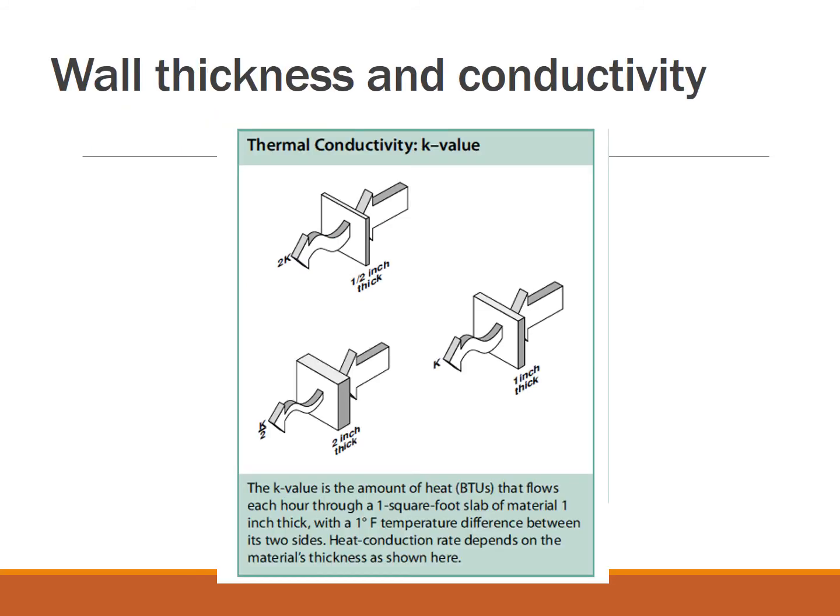And again, this is the relationship of thermal conductivity based on the thickness. You can see that the amount of heat that goes through the wall gets less as the wall gets thicker. Okay, we are not going to do that. We will look at the wall and find the resistance, which is the total resistance of the wall regardless of the material, because this could be made of different materials and has different K values. It requires a little bit more elaborate math. I'm not going to go into it.